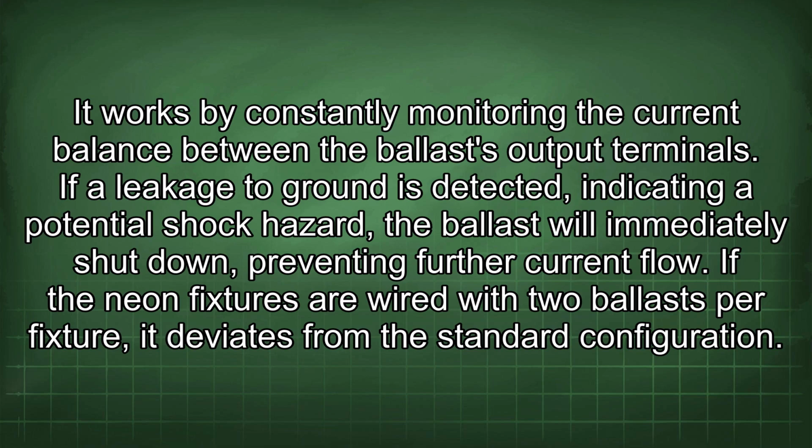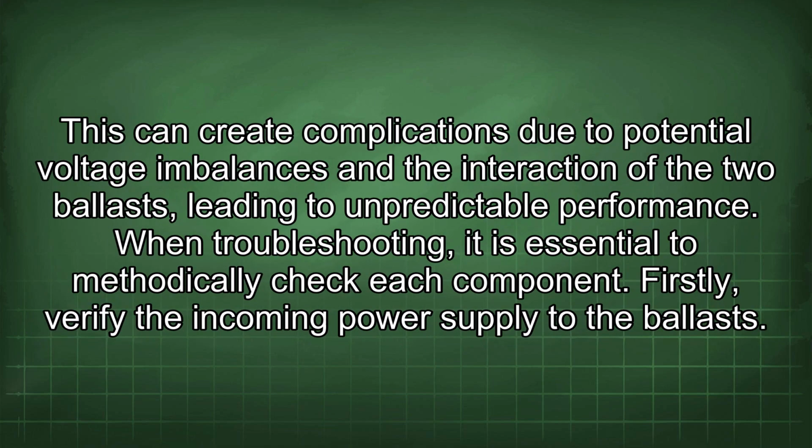If the neon fixtures are wired with two ballasts per fixture, it deviates from the standard configuration. This can create complications due to potential voltage imbalances and the interaction of the two ballasts, leading to unpredictable performance. When troubleshooting, it is essential to methodically check each component.